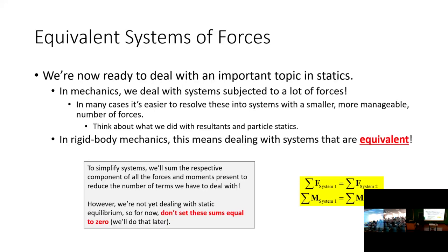But in the end, I think we understand generally what a moment is. A moment is an action on a body that increases its tendency to rotate about a given point, and we compute the moment about that point by taking the cross product of R and F, R being the position vector that starts at the point in question and points to the line of action of the force that's causing rotation.